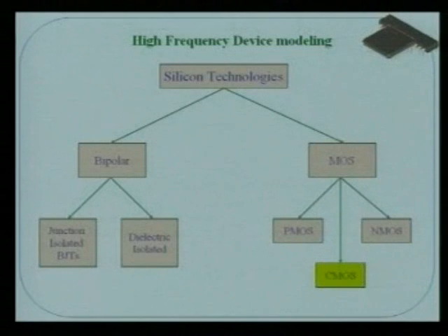And then you know that MOS devices having both the PMOS and NMOS are called complementary MOS devices. So our cup of tea is that CMOS. We will make CMOS our main component for making the RF circuits. Why? Because if you look at the power delay product, CMOS has the lowest one, it has minimum power consumption and less delay, but for ECL the delay is pretty low, very fast. But if you look at the power delay product compared to ECL or TTL, CMOS is the best one. So we are choosing CMOS for low power applications.